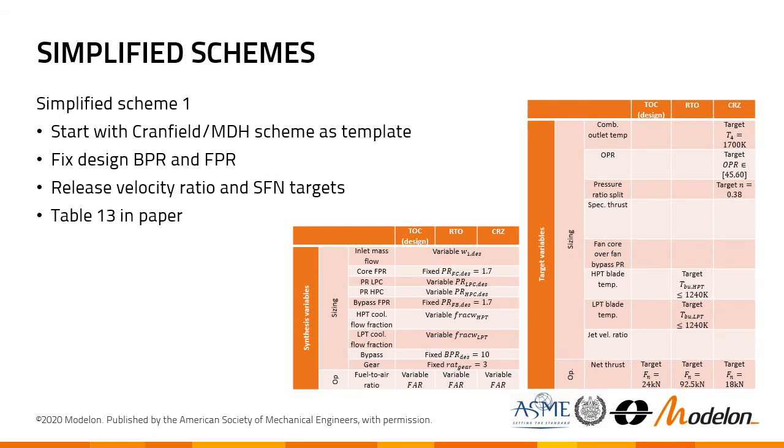Based on what we saw in the introduction on the state-of-the-art multi-point schemes, we can already predict this is likely too simplistic. The prescribed bypass ratio may yield a beneficial jet velocity ratio or not, based on engineering intuition, chance, or iteration. This could be the case or could not be the case. The prescribed fan pressure ratio may be easier to guess or predict due to a simpler relation between FPR and specific thrust.